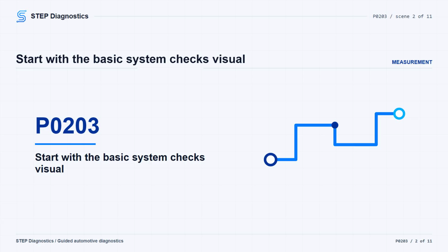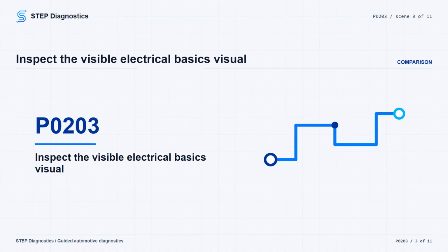Then, scan the vehicle. If other codes are present, check what they mean first. Circuit-related faults get handled before performance-type faults, because a bad circuit can make the rest of the diagnosis lie to you. If the concern is not present during testing, do not condemn a module or another component from that test session. Next, inspect the electrical side like a mechanic, not just a code reader.